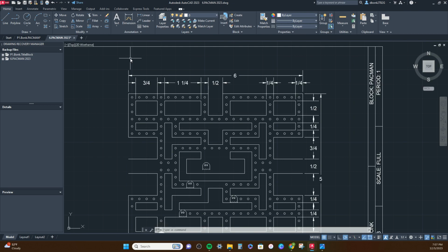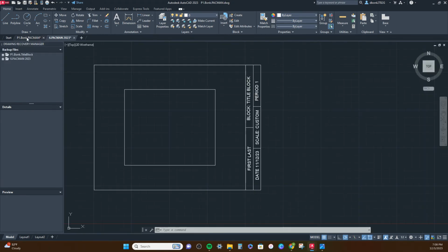So if you're somebody watching this online, you should have this on another display so you can actually count these things out, because you're going to count 6, and on the 7th you're going to make a 4 by 3 cutout, and you're going to do a 2 by 4 cutout, a 4 by 3 cutout, and the same thing on both sides. And over here is important numbering that you're going to want to follow along once I get this going here. So back to my Pac-Man drawing, what you're going to start off with is making a copy of this vertical line, going 24 of them to the right, which is done.